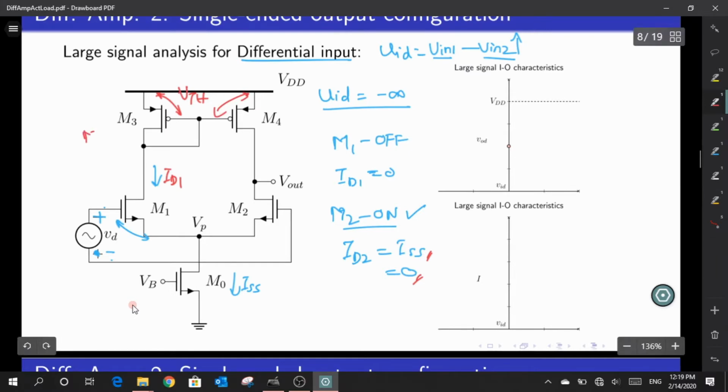Okay, so in this case my M3 is also off, just because the current is not drawn, which means that my M3 is cut off, and the same value of VGS is being copied onto my M4, which has the same similar setup. So due to which, what happens to my M4 then? That will also be off.